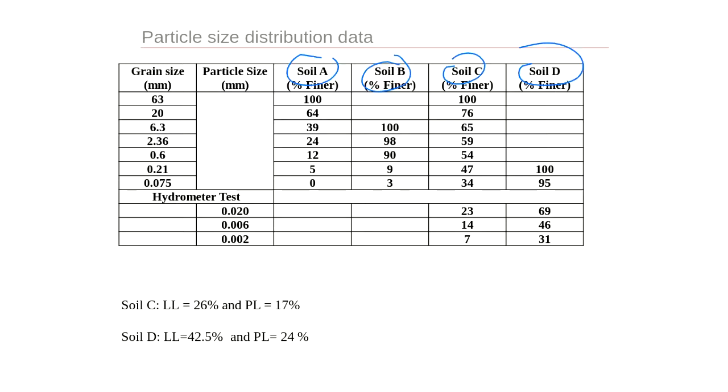And here it says results of hydrometer test. Hydrometer test is a different test. It's not like the particle size distribution or sieve analysis. I talked about the test in the lecture, where we have fine particles swimming in the liquid, and then we measure the density of that liquid based on the velocity, how fast those fine particles settle.